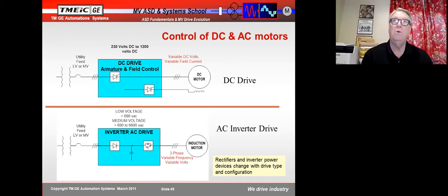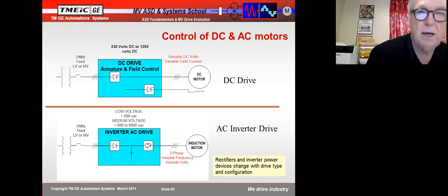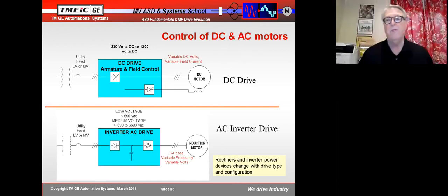Well, the speed there wasn't really important and it would change depending upon the diameter of the coil. What was important was the torque because we wanted to control the tension. And so DC drives were very good at that. By contrast, AC drives were not very good at either of those things. They weren't that good at speed control, although you could put a tachometer on them and get a very precise speed. They couldn't control torque because they have nothing in them that allows them to sense what that torque is.